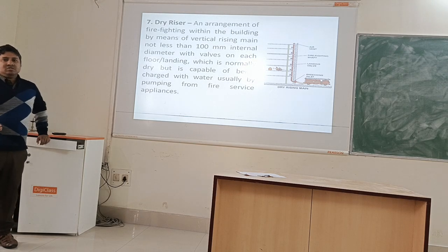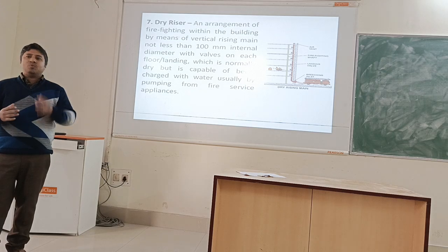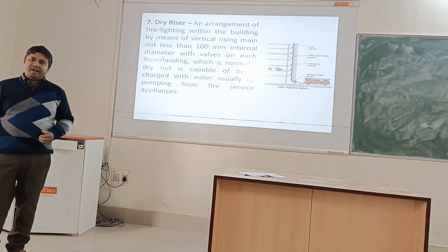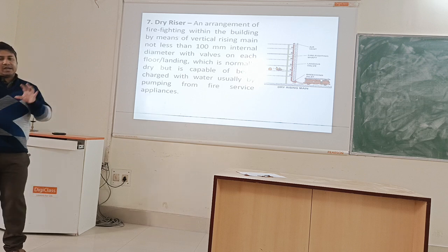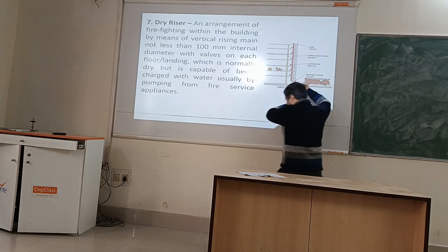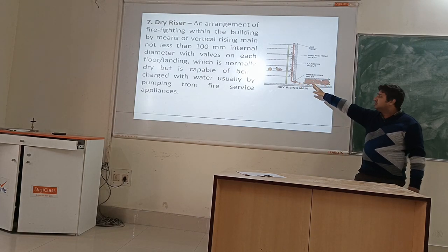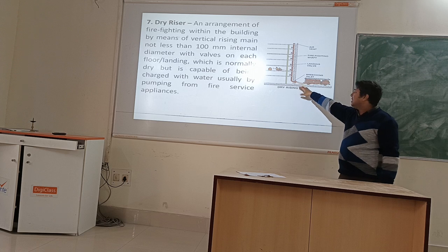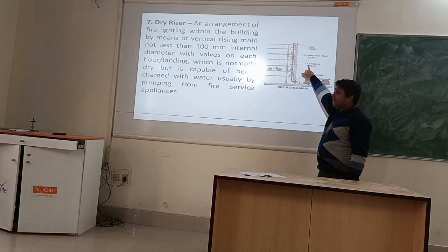In the dry riser, we have an arrangement of shafts, pipelines and valves to every floor of a multi-story building, and these pipes are capable of handling the fire extinguisher trucks. Water can be supplied from the fire truck, and there may not be any permanent water supply. When the truck comes, they attach their hoses to the landing valve.